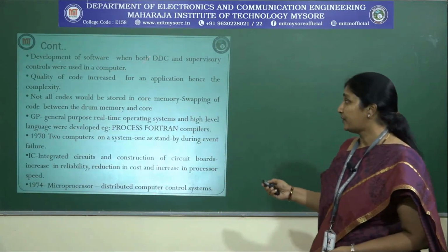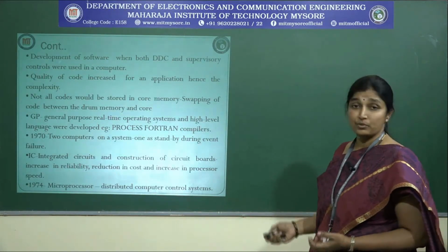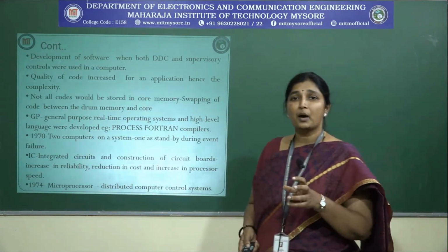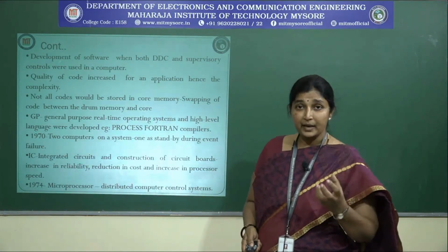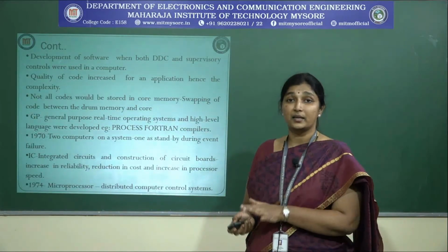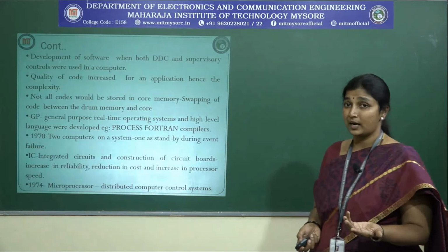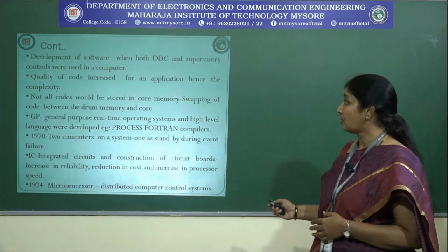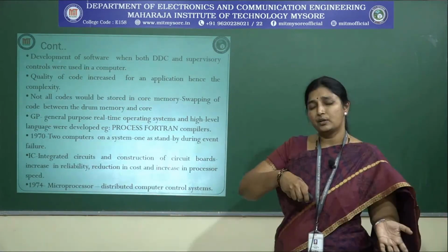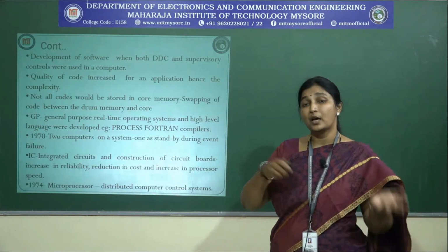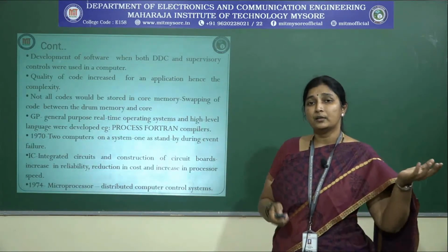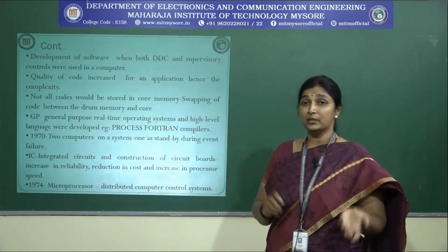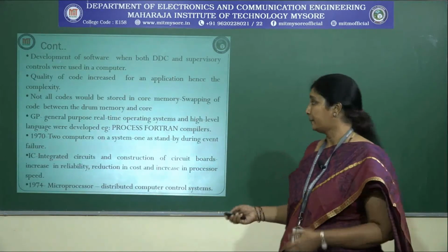So the development of software when both DDC and supervisory control were used in a computer, and the quality of coding increased because it was not just about the storage in ferrite but also using a drum, which is an external hard disk, which is replaced by an external hard disk now. So now the quality of the coding also increased as well as the complexity. So we used to have another concept called switchover mode. So switching the core contents, the program from the ferrite core to the drum and from the drum to the ferrite core came into being.